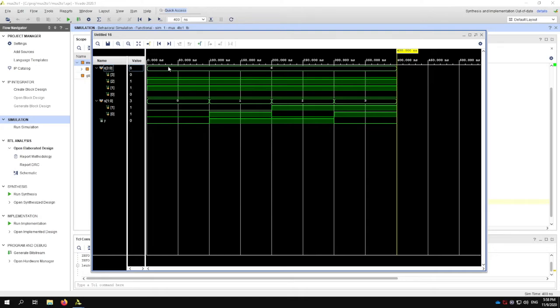X, as I can see from here, stays the same. So these lines mean 0, and these mean 1, the value 1. X doesn't change throughout, right? Which makes sense because I never change the value of X. But my selector does. My selector starts at 0,0, then 0,1, 1,0, and 1,1, which is decimal 0, 1, 2, and 3 respectively.